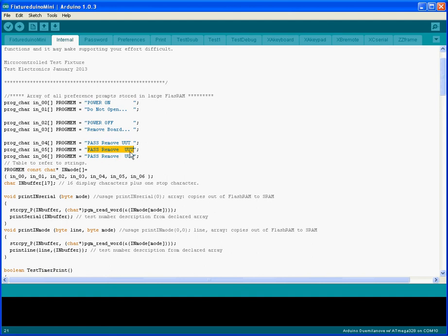So you go up here and you look in what's in number 5 and what's in number 4. Number 5 is when it passes, it prints this. If it doesn't pass the first time and it passes the second time, it prints this. Now there's just a little tiny difference that the test technician is not going to know, but the test engineer will recognize. And this is just so you don't have the test technician someday dividing the test results into 3 piles. You always want them to put a test in a pass or a fail. You don't want them to put it in a pass, a kind of pass, and then a fail.